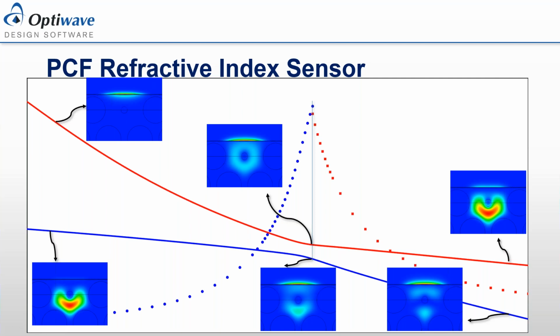What we have here is this upper band corresponds to the plasmonic modes. As you can see, there's heavy dominance at this interface between the gold and analyte and gold and silica. And then down here, this is our fiber core mode and how it adapts as we shift towards the phase matching condition and start shifting away from it.